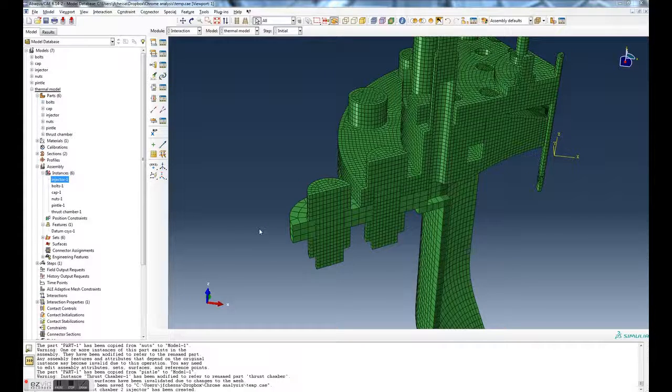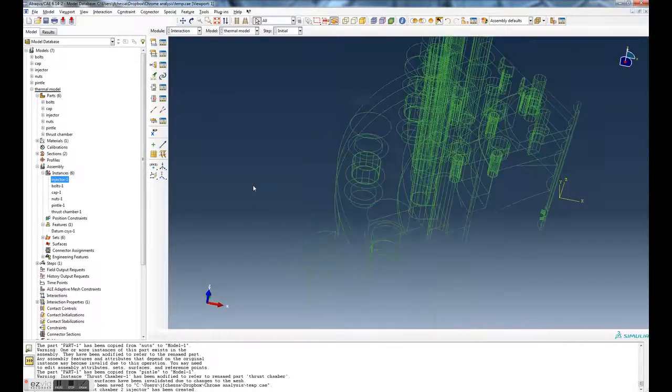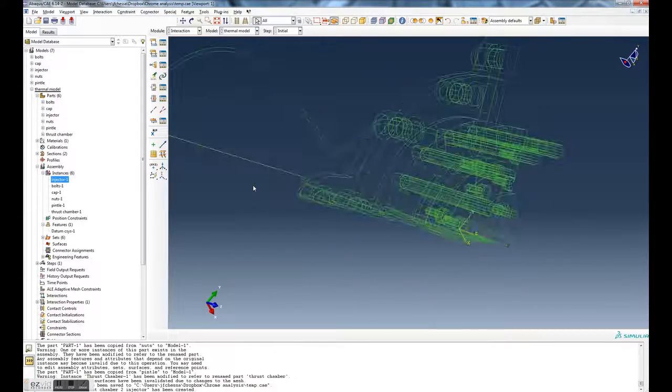The trick is knowing how to get the global node numbers from the connectivity matrix, how to get the node coordinates from the nodal coordinate matrix, and then to use that mapping to figure out the scattering factor for where the local stiffness matrix goes to the global, okay? All right, the rest of it's pretty straightforward.